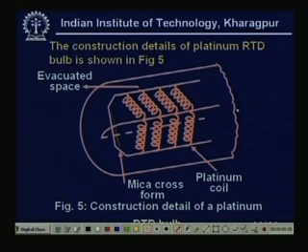But if I use it for dynamic measurement, in the case of a thermistor, instead of balancing the bridge, I will take the unbalanced voltage, convert it into the current domain, and calibrate it in terms of temperature. That is quite obvious. But in the case of an RTD, it does not matter, even if you use an unbalanced voltage to make the measurements.